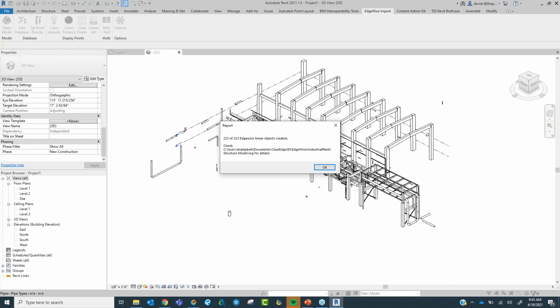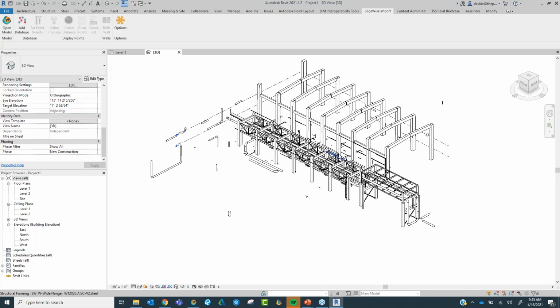What I would say would help you there is probably planning. Like what I like doing is if you can get an idea of the layout of the building and get an idea of how you want to plan your setups, right? Because obviously we don't want to do too many setups, but we want to do enough to where we get all of the data that is going to be good enough to bring into something like Edgewise or even Revit for that matter. We want to be able to see it. We don't need these big holes and gaps in it, right?